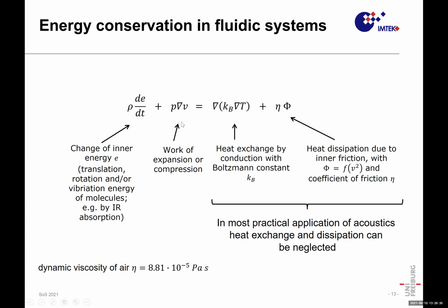Then, of course, we have the work of expansion or compression whenever we squeeze or expand a volume. Also not a situation that we will do to microphones in higher excitations. And this is balanced, of course, by heat exchange, by conduction with the Boltzmann constant. So whenever you have temperature gradients, then this will also cause an energy effect. And then inner friction is also something. We have, of course, gas molecules hitting each other. This is a kind of heat dissipation. And of course, there is a coefficient of friction with this.